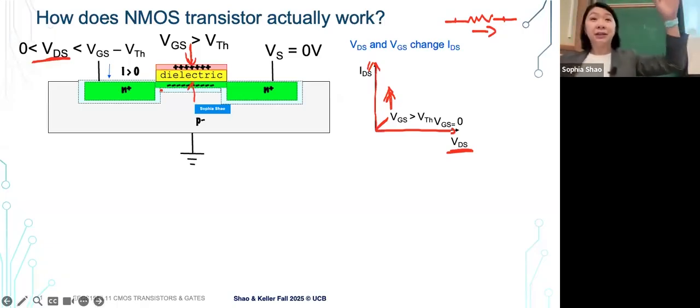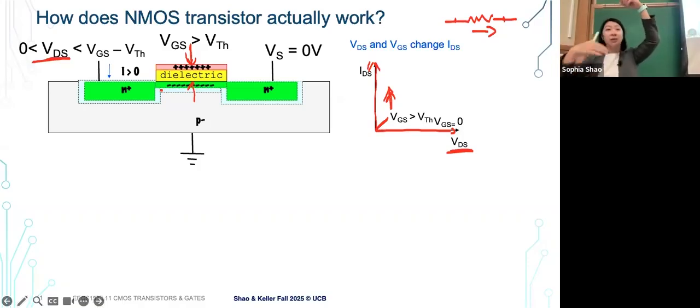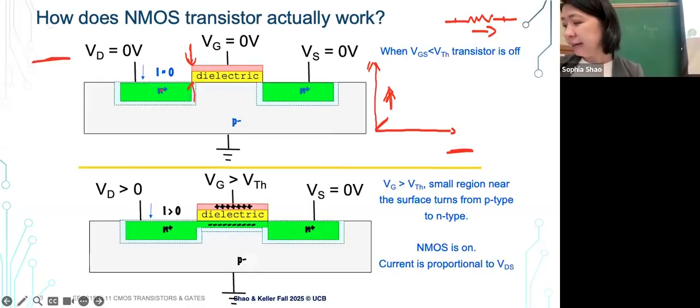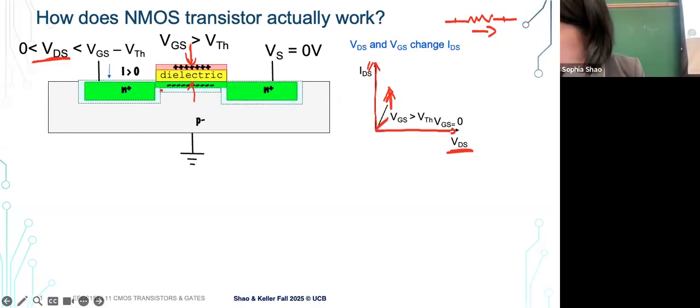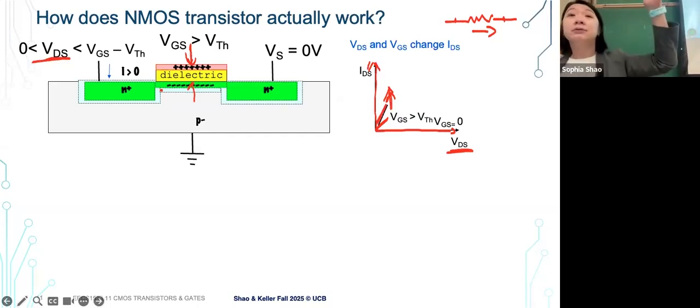The channel is bigger now, right? Because you have higher voltage on one side of the capacitor, you attract more electrons on the other side of the capacitor. You have a wider conducting channel. So when you apply a higher gate voltage here, we see increasing current for the same drain and source voltage.